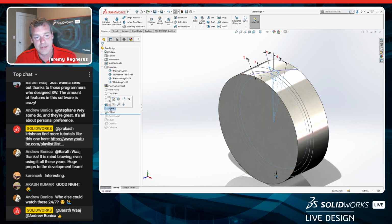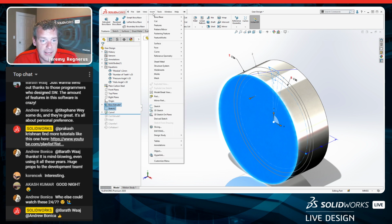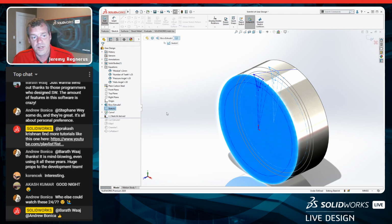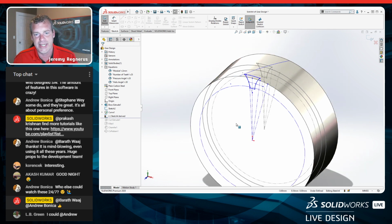I want to copy this sketch, number 2, onto this face. So I held my control key there, right? I selected the sketch and the face. And I can go up here and go to insert, and there it is, derive sketch. And what does it do? It creates a copy of that sketch on that face. But it's not just a copy. If I change anything in the first sketch, the second sketch always stays up to date.